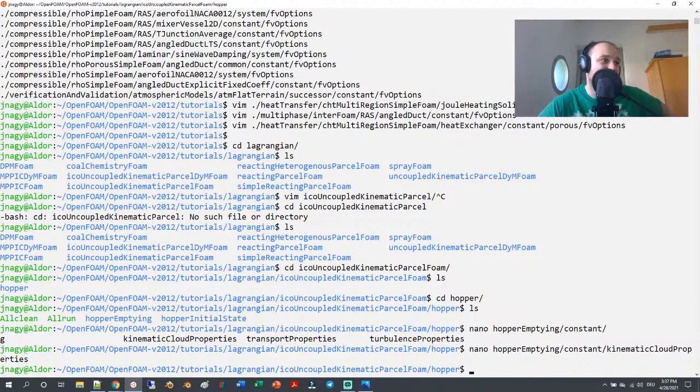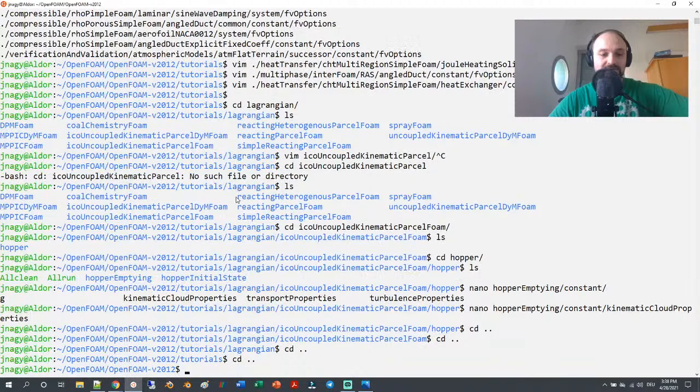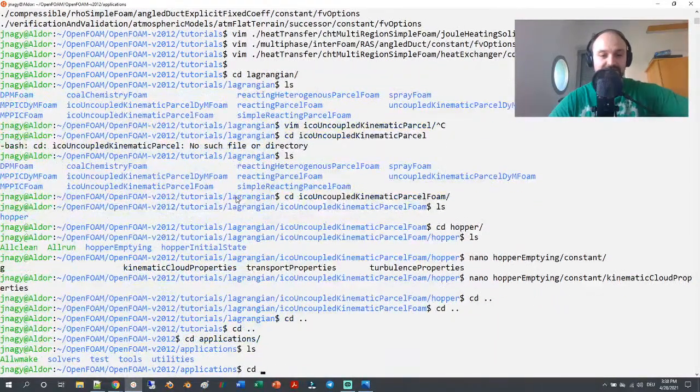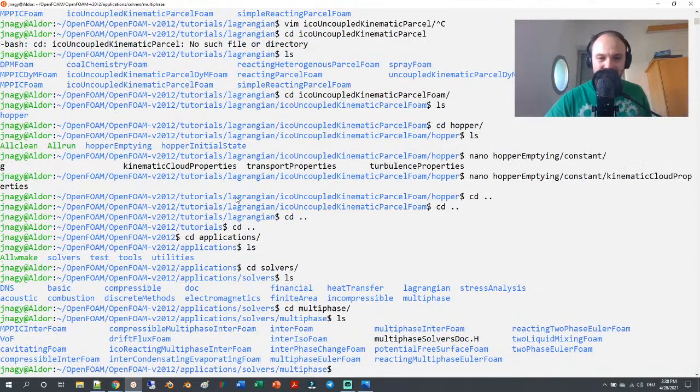Which OpenFOAM solver would you recommend to simulate mass transfer between? That's a good question. I don't know. I would have to check this out myself. So again, mass transfer gas dispersed phase. So I'm guessing this is the Euler. So there are solvers, multiphaseEulerFoam here, interfaceChangeFoam.